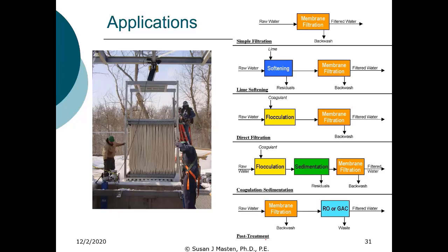So think about this with your design: you need a plant that operates as effectively for those 400 people in the middle of winter as for the 15,000 in the summertime. It's quite the challenge. So both water and wastewater treatment plants have to operate with that kind of variability in flow. You can also use it for softening.